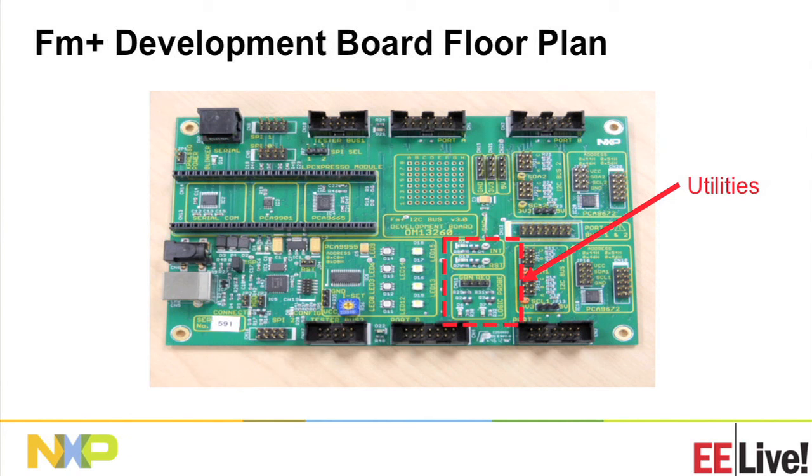Finally, we have a couple of utilities. There's sort of a little logic probe down here. It's an LED with a FET isolator so that you can probe a signal and find out whether it's logic 1 or logic 0 and not have to haul some lab equipment in or wire up something else to find out the voltage level.